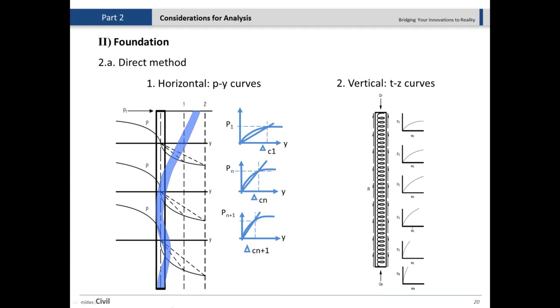But I don't recommend that, because we have the active behavior of the soil and also passive forces. When you're simulating this pile, or a retaining wall or any embedded structure in the soil, when you push it from left to right, we're going to see some forces from here, and also some forces right here on the left side. That's pretty important. Even the simplified methods of Bishop and all those also require those forces.